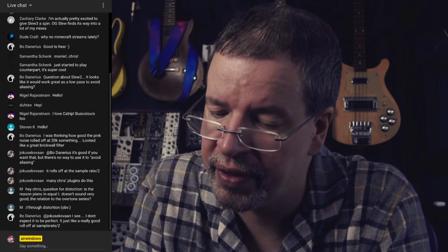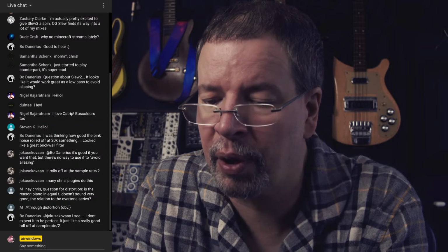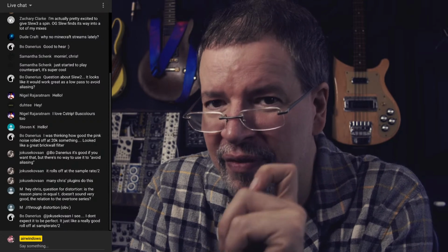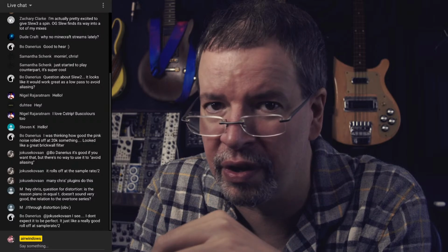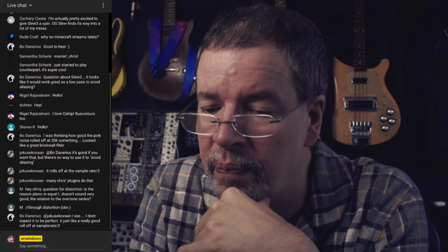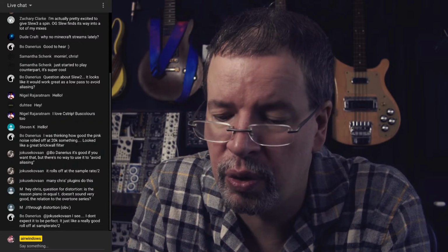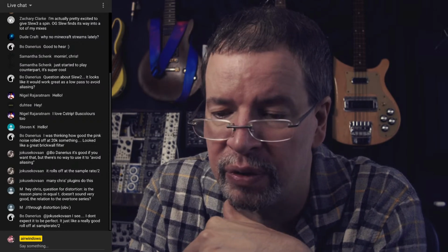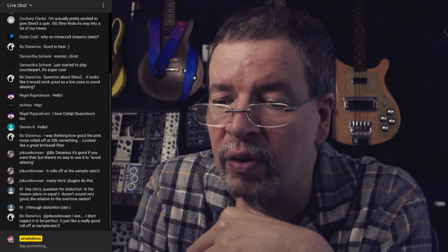He had a phase shifter in there. And it was thought to be very difficult because you couldn't get the part, and the part was a Vactrol. And now I know that a Vactrol is nothing but an LED and a CDS cell, and I have dozens of CDS cells kicking around and can get them as well. The deal with the Vactrol is that he wanted to use exactly the right kind for predictable behavior, but the other thing about Vactrols is you can get your behavior in various ways.